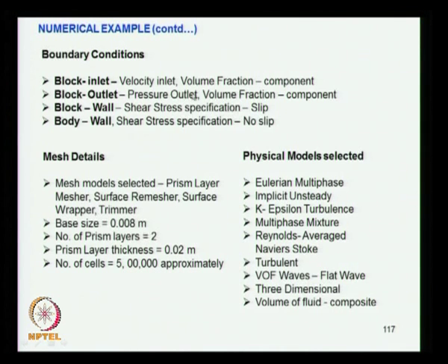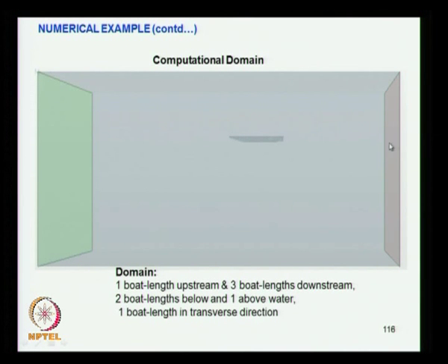For the boundary conditions, we use velocity inlet, volume fraction and components. Here this is the inlet boundary, and this is the outlet boundary.